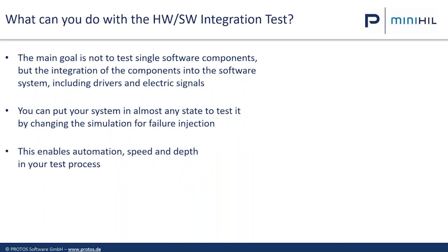So now what can you do with this hardware software integration test? The main goal is not to test single software components, for example, the motor control or something like that, but the integration of the components into the software system, including the drivers and the electric system and electric signals such as PWMs, CAN bus, and so on.